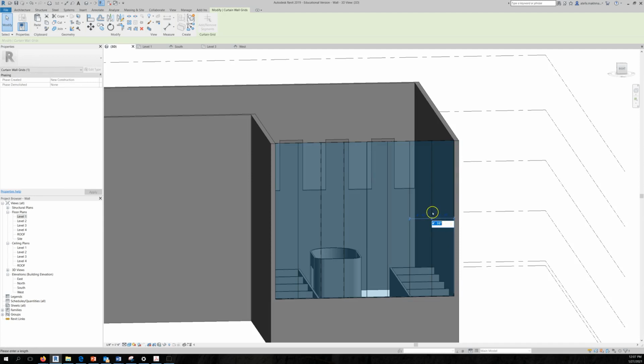If I want to change the dimension for 2 vertical lines, I need to select that vertical line to be able to change this dimension. Students in the beginning click a lot on the horizontal line to change a horizontal dimension. That does not work. 5, 5, and 5. Did we go wrong way?